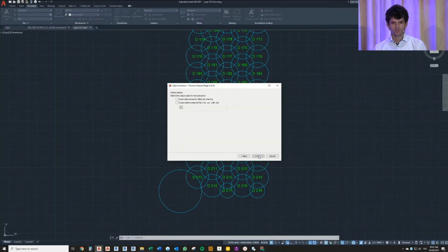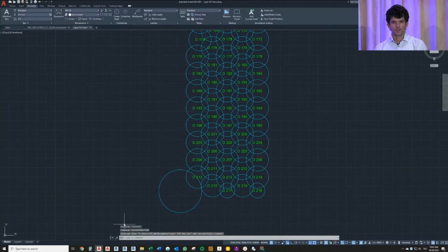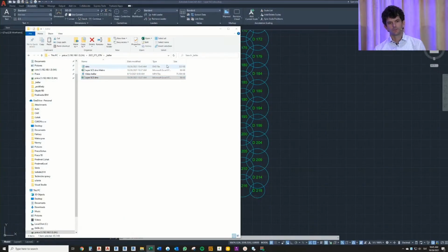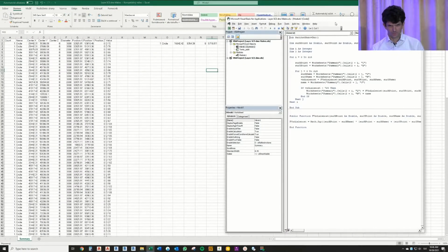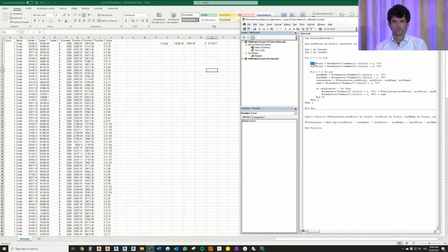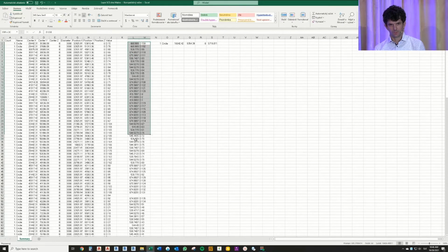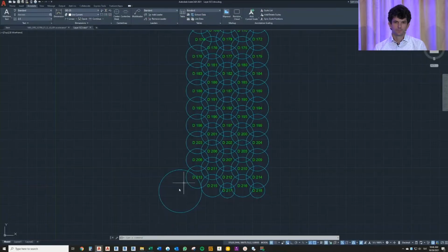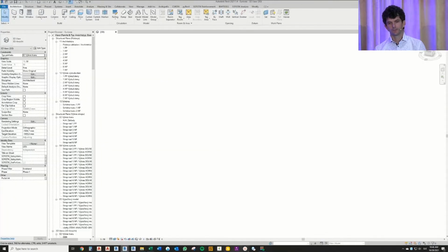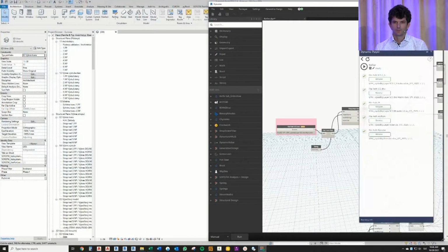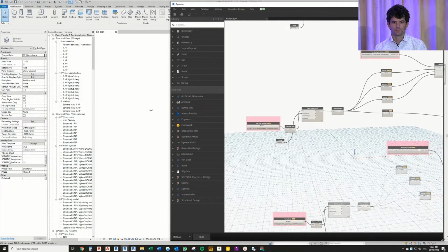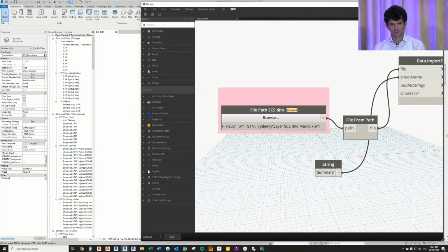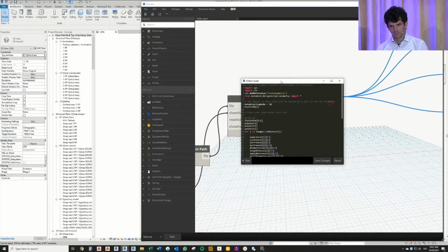So we were able to do it in this way, and we loaded it into Excel spreadsheet. We were missing also other components such as the Z coordinate and the depths. We used for that Visual Basic. We produced an Excel spreadsheet this way, and we could use that as an input to Revit. Then in Revit, we used a Dynamo feature or software in which you are able to create these little pieces of code, and what it means are little scripts. That means it loads the information from Excel and it creates individual components, and we use the components used by